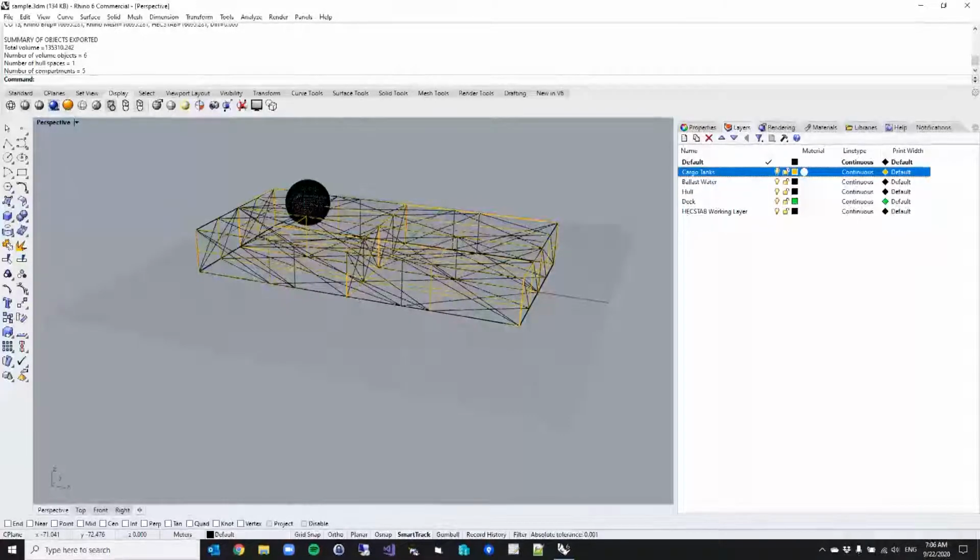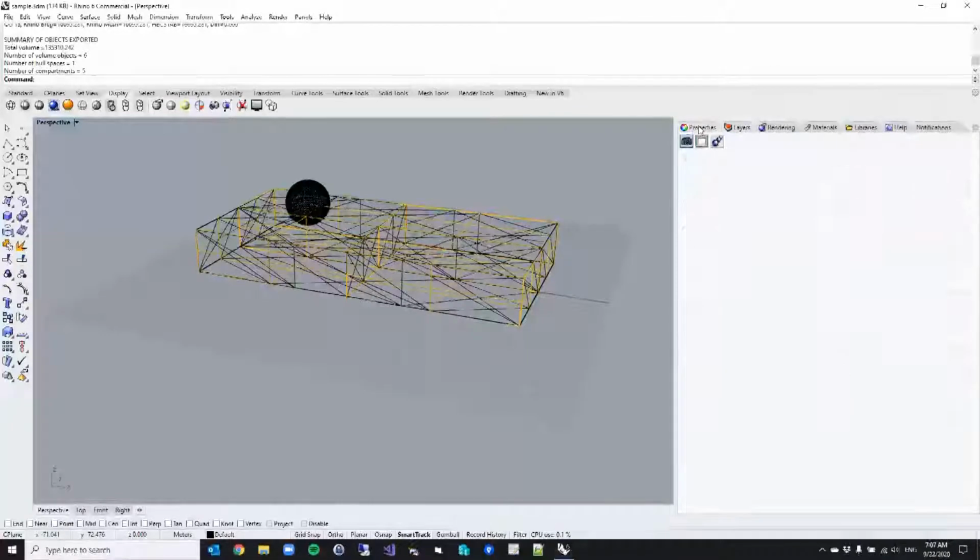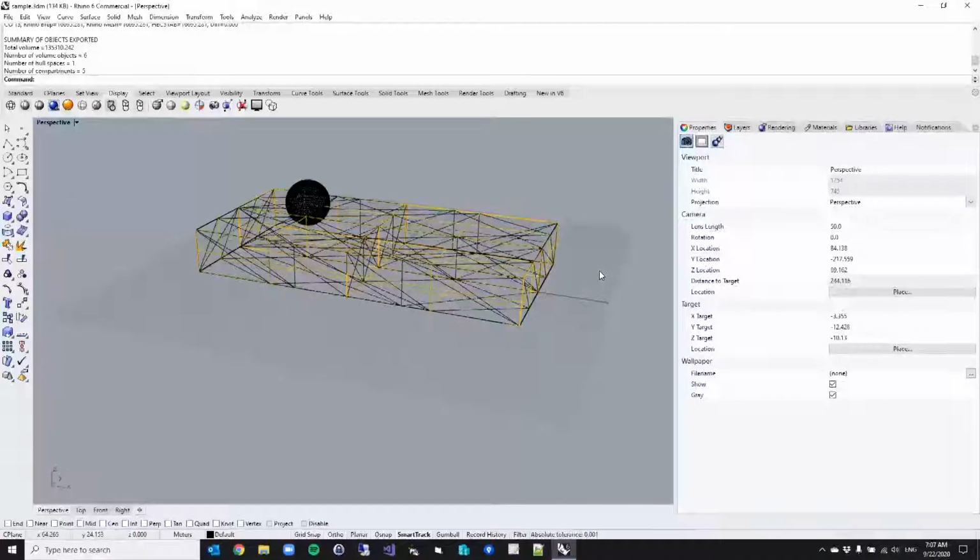If you get a hull out of part surfaces with small gaps between the edges, can HexTab handle that? I believe if there's gaps, it's not going to be defined as a closed poly surface. That is one of the key modeling issues that we have, and we've seen this as we work with other people's models, that not everything is immediately a closed poly surface, and sometimes there's some repair, some tweaking or polishing that needs to be done to a Rhino model to get there. But that would all be done on the Rhino side. We basically need the Rhino model to be able to create the closed mesh.